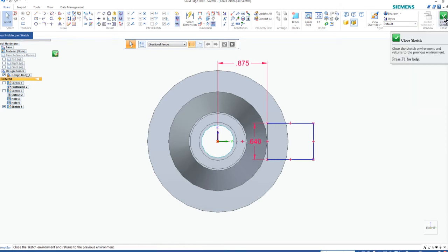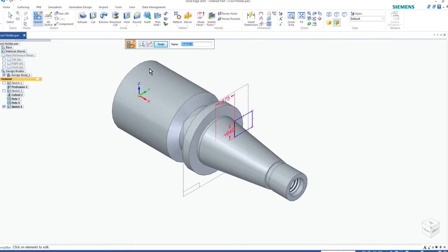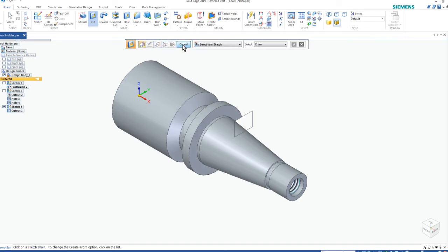Let's finish our sketch. We are going to do an extrusion this time, or actually, cancel. We're actually going to do an extrusion cut. We're going to select, click OK, and then we're going to make sure that it's going to go through to next. Make sure that the arrow is pointing into the material. If you click here, you see the little exclamation mark coming in. That's saying you're trying to cut air, which means nothing. So make sure it's into the material, left click, finish, cancel.